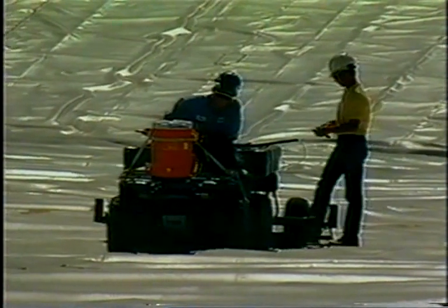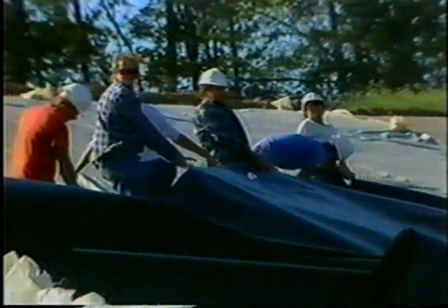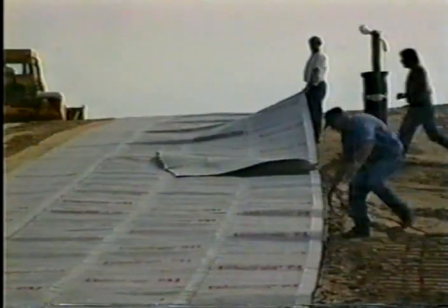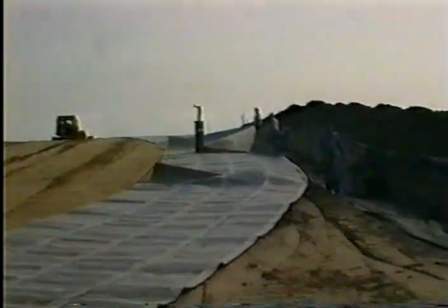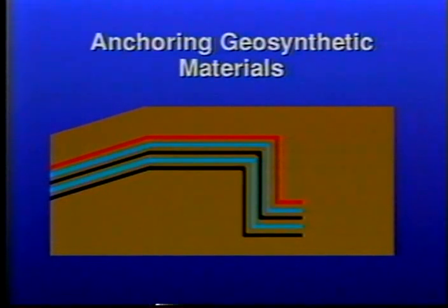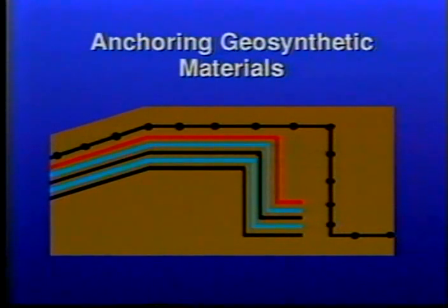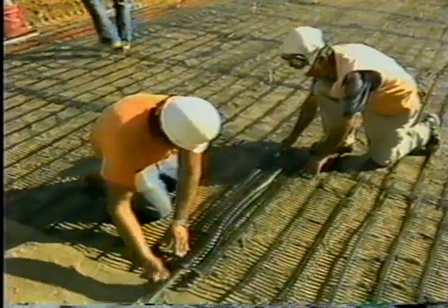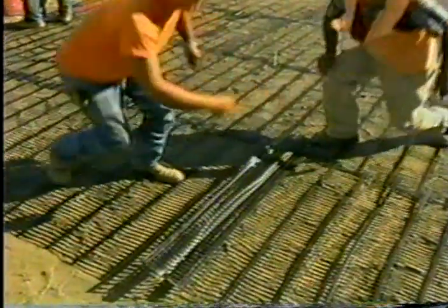Let's just consider for a moment some critical stages during installation. Geosynthetic materials need treating with respect. They can be torn during handling or damaged by welding. Every flaw must be found and repaired. Installing materials around pipe joints, inspection chambers, or vents needs special care. Materials must be anchored firmly in a trench at the top of the slope. Geogrids must be secured in their own anchor trench. Joining the ends of geogrids and tying adjacent lengths of grids or geonets must be according to project specifications.